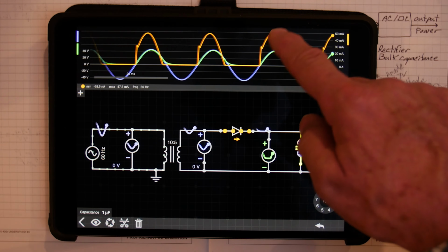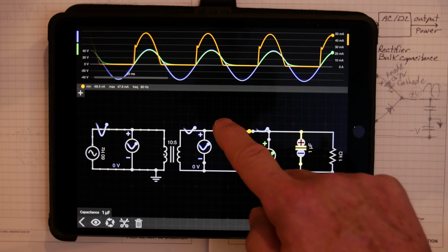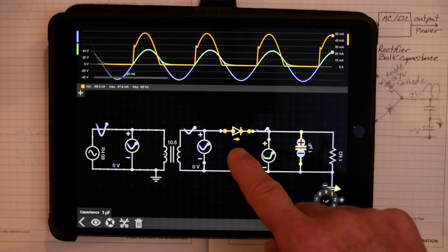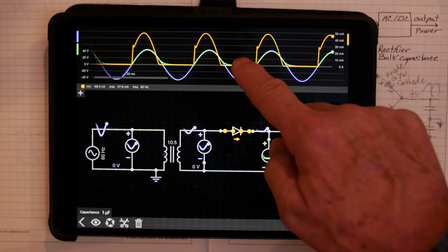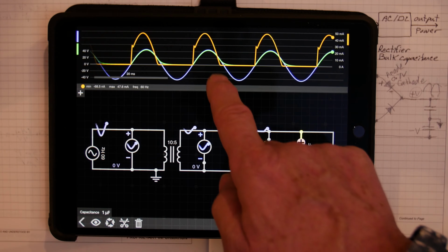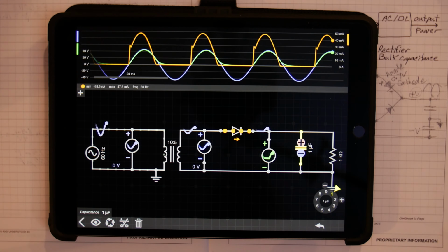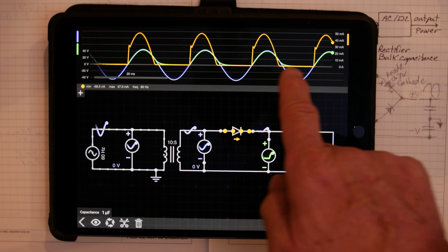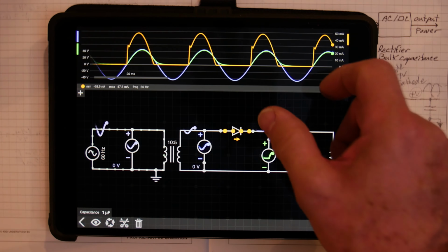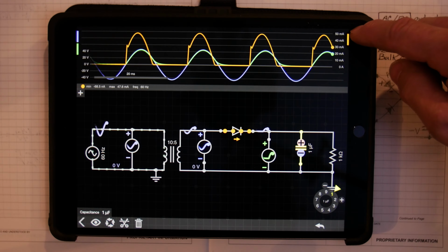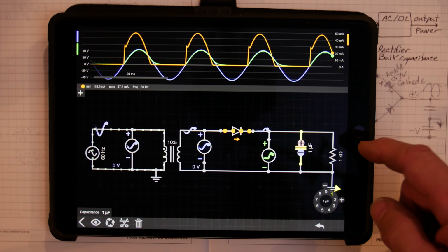So now you can see the orange waveform looks much more almost sinusoidal. As soon as the blue crosses the green, you get kind of an inrush current, which we call it, because the capacitor is drained, so it charges quickly, and then once it does, it kind of follows the green waveform. But once the blue drops below the green, the orange turns off again. So what's important about this is right now the orange waveform is on for kind of a long period of time, which is good because the value right now is going up to about 50 milliamps. Okay, it's actually 47.6 milliamps.